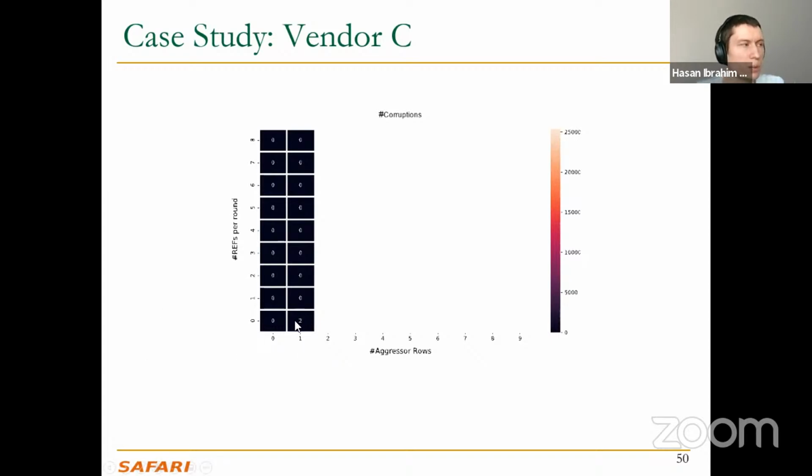And then here, with a very small chance, we were somehow able to circumvent the TRR mechanism because there are no refreshes. And these are not retention failures because we complete the aggressor activations and these refreshes in time smaller than the typical refresh period of 64 milliseconds. So without hammers, these rows do not fail. As you can see over here, when we do not have any aggressor rows, we don't get any bit flips.